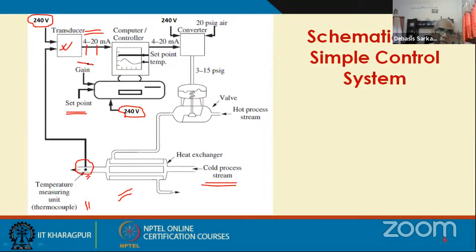So then the gain will be an input, or proportional integral control, proportional integral derivative control. All these things can be written. So depending on the algorithm that you use, it will have different inputs for the controller as well. Those gains of the controller, right? You know that those are typical symbols, K, tau I, tau D, etc.